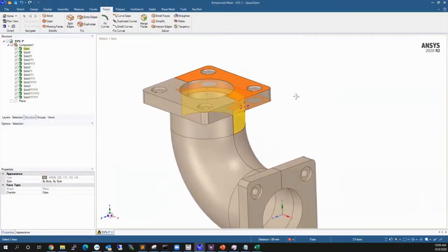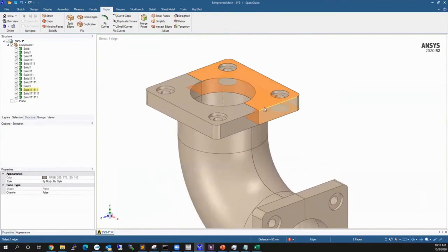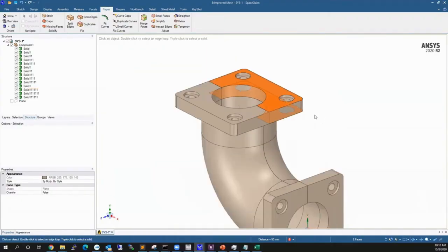Obviously, this is pretty advantageous for a couple of different reasons. Number one, we'll have a hexahedral mesh, and number two, we can determine how many elements we want through the thickness here. We typically won't get those super sharp, jagged shaped elements that you guys saw before.